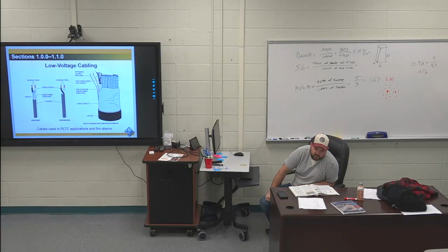And then you can have direct buried cable. So has anybody ever seen UF cable? It's like gray Romex. With generators that run right there, you run UF cable. That stuff's super nice because I think it's got to be 6 inches underground. I think down here it's 18. If it's by itself, I think it's 12. If we put it with gas, I think you have to do 18 and 24.